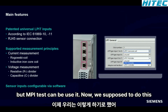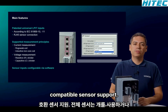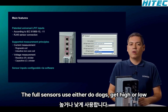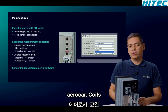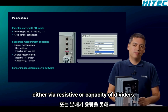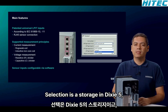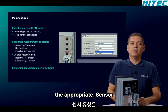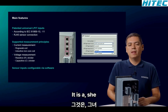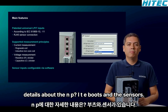But which LPITs can be used now? What measurement principles do these compatible sensors support? The current sensors use either the Rogowski coil or low-power iron core coils. The voltage measurement is carried out either via resistive or capacitive dividers. Of course, the selection is stored in DIGSI 5, so that the appropriate sensor type is set as part of the parameterization. Lars, now can you tell us more in depth about the LPIT inputs and the sensors?